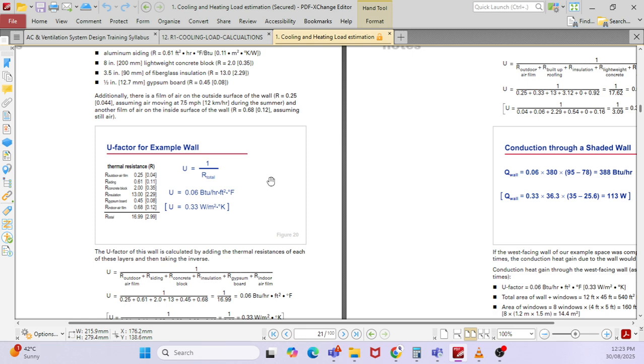See, you are talking about the resistance of the material. The material resistance will not change, internal or external. But for the external wall, they will add some insulation to reduce the U value. If you go to the internal wall, they don't need insulation because both sides are air conditioned. So in that case the U value will be different, but it does not depend upon the temperature.